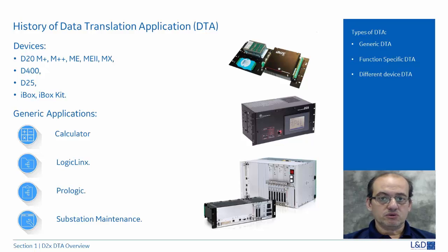Now, what you have to know as a user of the remote terminal unit is that if you're thinking of a certain application or a certain logic, let's say you want to OR all your digital inputs, we could have a DTA that will service your need. For example, the Common Alarm DTA, Data Translation Application. The Common Alarm DTA will allow you to take a whole bunch of digital inputs and change them into a single alarm point, all right?